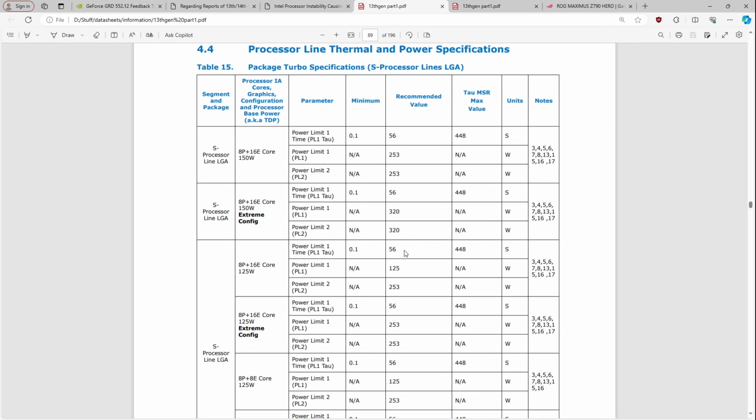To be fair, on AMD motherboards, one potential way of getting around the power limits is if the voltage regulator isn't very good at measuring the output power, then that'll mess with the power limits. I'm pretty sure even with Intel CPUs that's a potential way of messing with the power limits from the factory, but I've never seen a motherboard vendor intentionally do that.